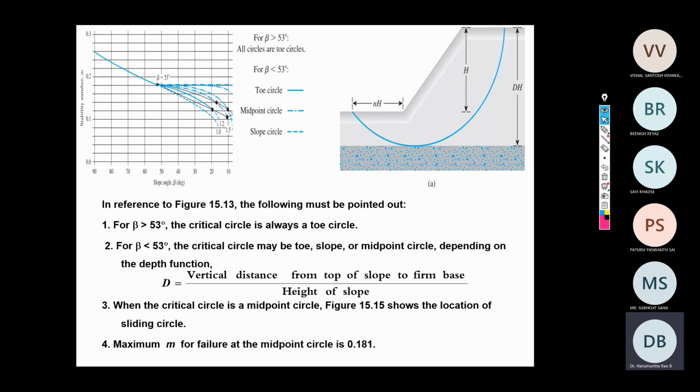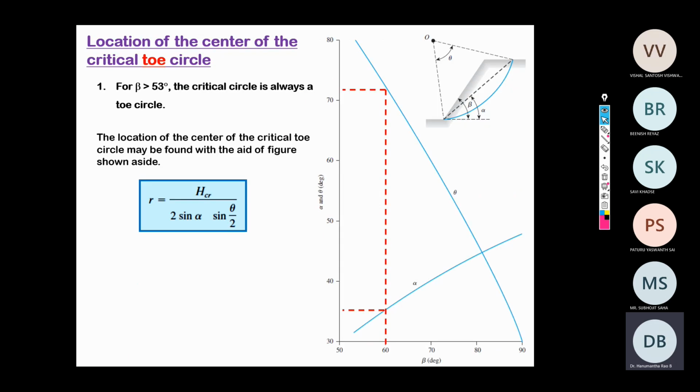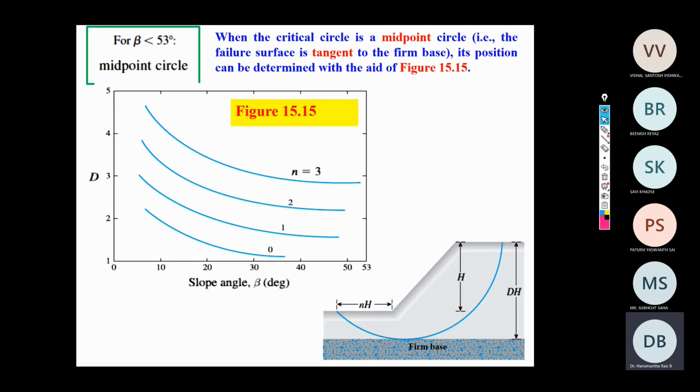Okay, so now what about the infinite slope? Is this correct, sir? It is not exactly, because whenever there is moisture in the soil, it always tries to reduce the shear strength component. If you follow that logic, then more water in the soil would mean more shear strength, but that is not true.